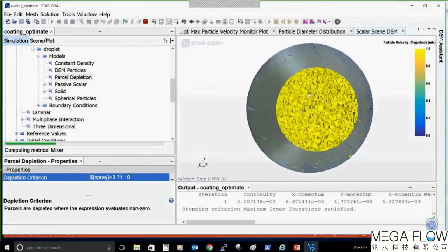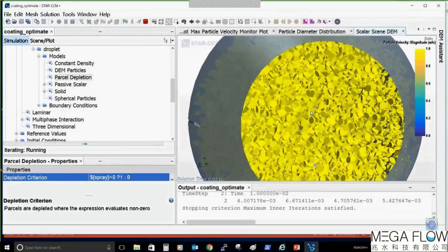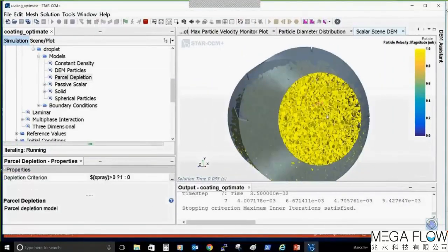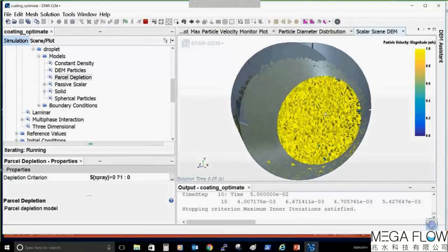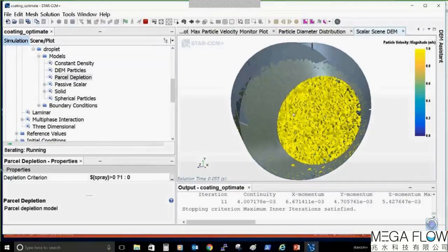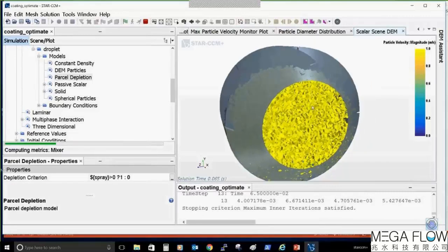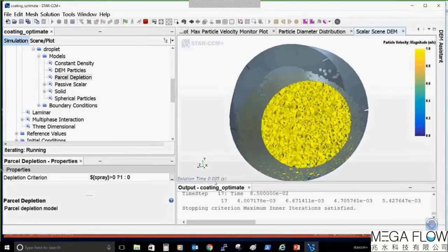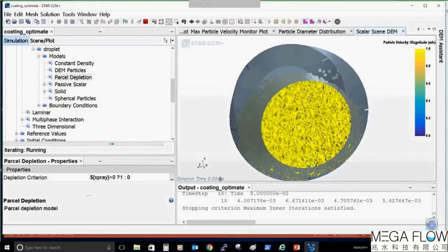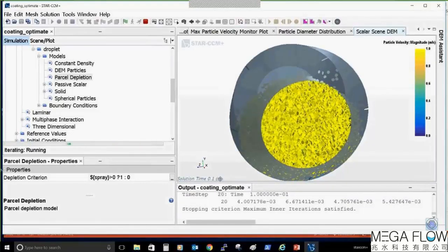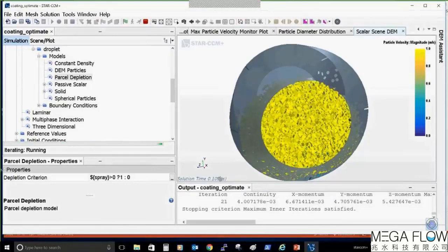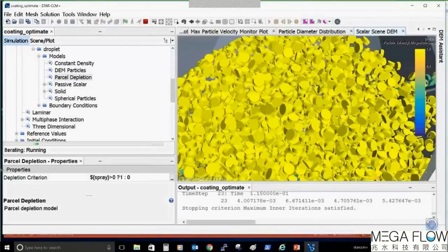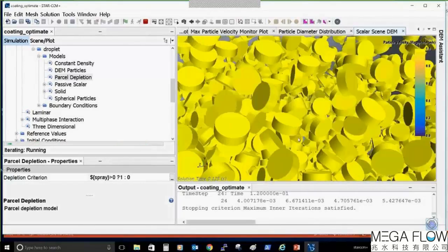So you see there are already 8,000 droplets injected instantaneously into the simulation domain, exactly as we specified in our settings. And at some moment, when the solution time, which is shown in this corner, is 0.22, the droplets will start to be sprayed on the top surface of the mixing cylindrical particles. Those particles are small cylinders, as we set up previously.